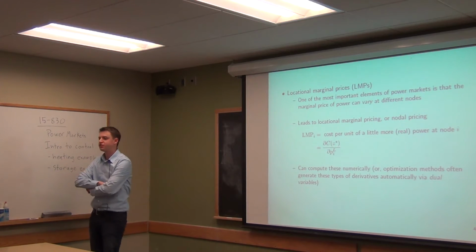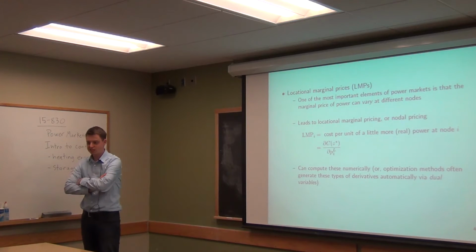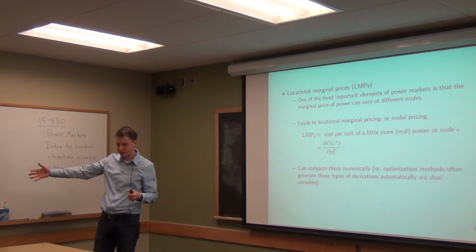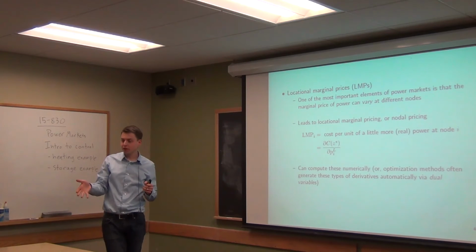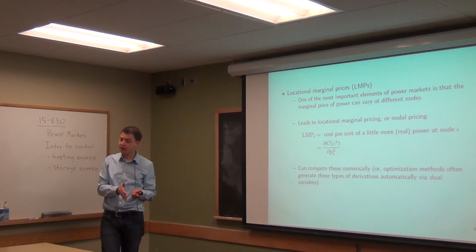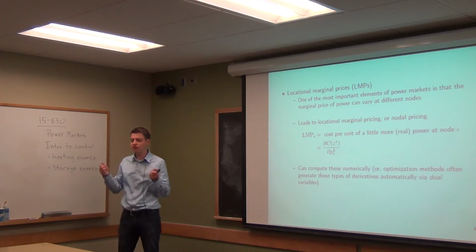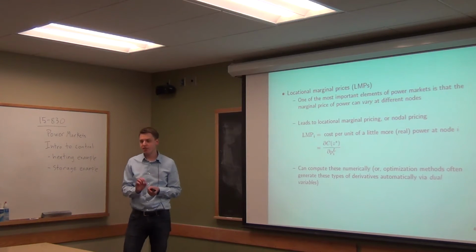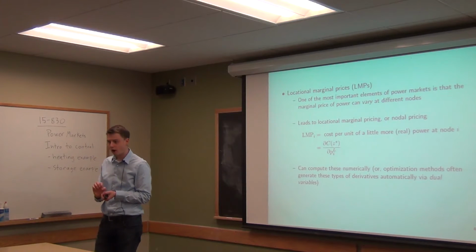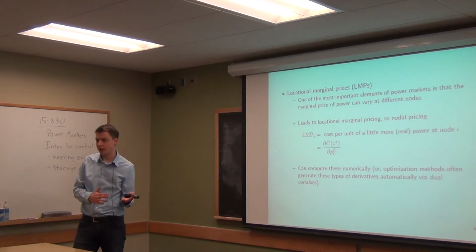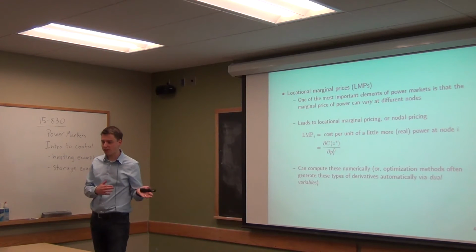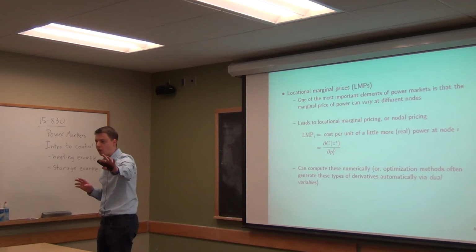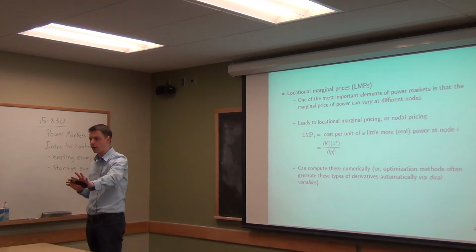The problem with reactive power is the losses of, quote unquote, reactive power, which is a little bit strange to say, but basically the amount of reactive power that dissipates over a transmission line. Reactances are typically much higher than resistances of transmission lines. They have a relatively high inductance versus their resistance. Because of that, the actual losses you get in reactive power are very big compared to losses in real power. And so reactive power does not really operate in the same sense. You can't really hope to provide reactive power to a location very far away. You'll just lose so much in transmission that it makes it very uneconomical.